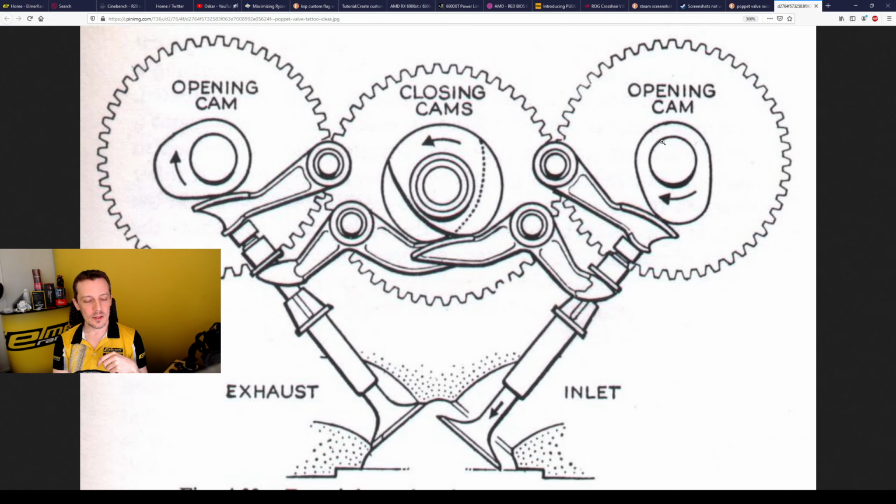So yeah, we have a typical cam. This is what would be a finger follower type opening, which is completely traditional with spring type valve systems also. So we have a camshaft here. I'm looking at the opening cam here on the right, in case you don't see the mouse cursor. This rotates and pushes on a follower, which removes the need to have a bucket here. We'll go through that a little further also. And this pushes the valve open, basically.